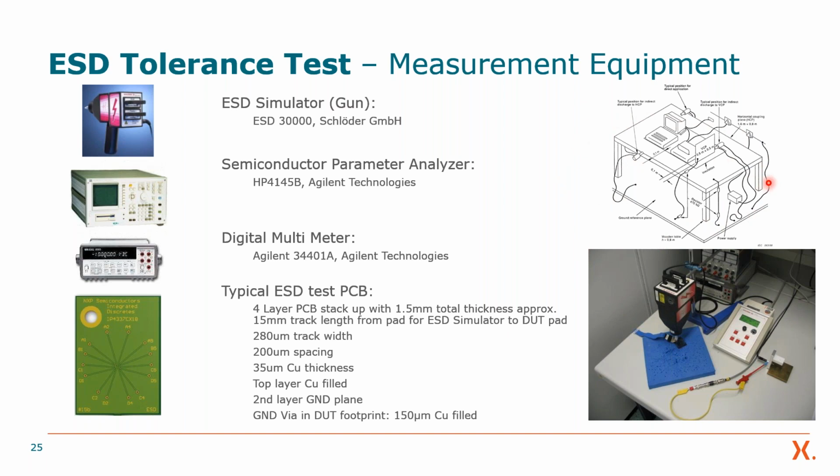So actually there are a lot of tests that you have to conduct when you want to comply with the norm, like shooting into these vertical coupling planes and having air discharge and stuff like this. But for a single device, this does not tell you anything. The only reliable and repeatable thing you can do is to directly shoot on the device itself and to consider it as a system. Air discharge also does not really make sense, and the repeatability is not very good, especially because the single devices are so tiny.